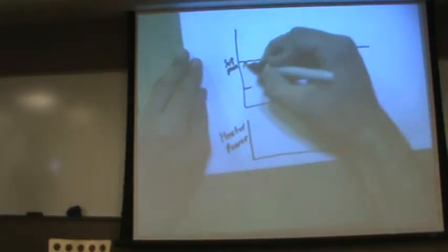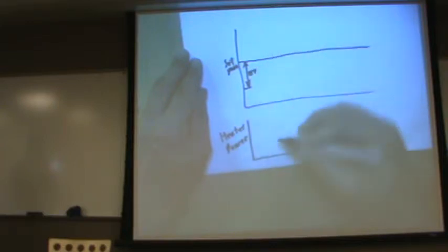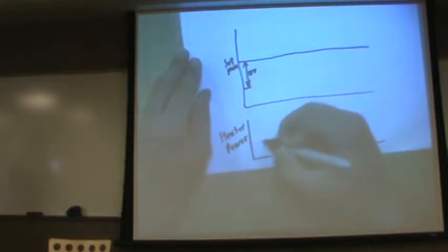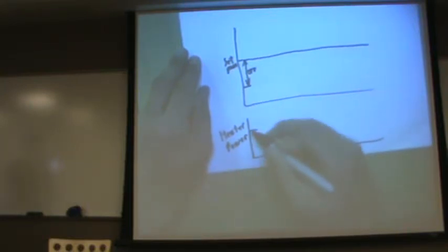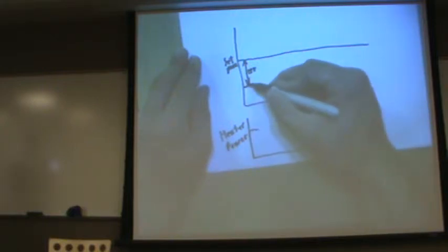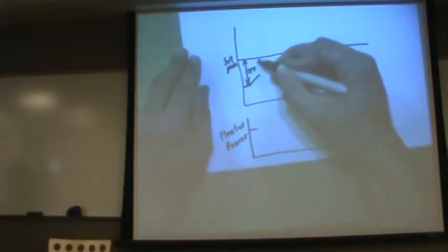So your temperature's down here. You want to take this error and multiply it by some gain, which is usually called Kp, to get your heater power. So now you're turning on your heater, that heats things up, that brings up your temperature. Now your error is smaller, you can turn down your heater a little bit.